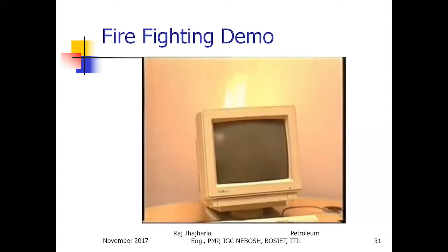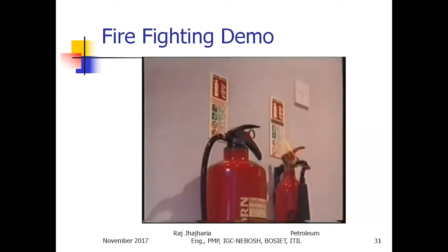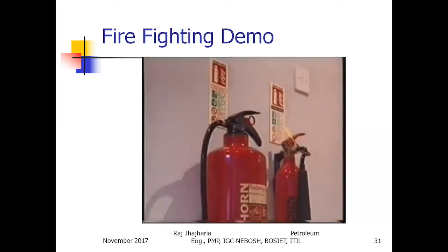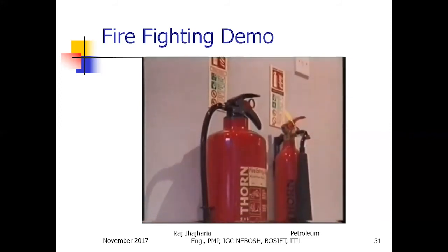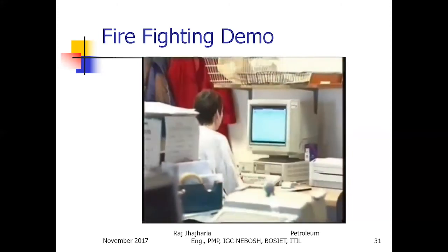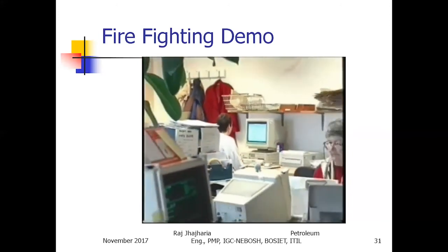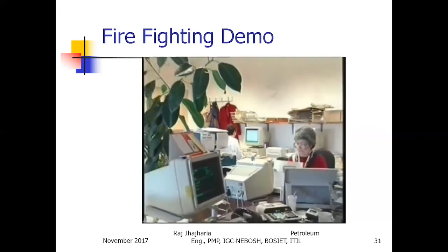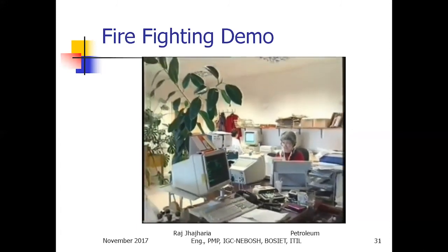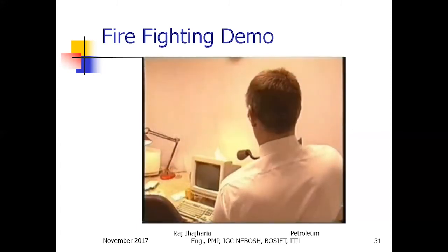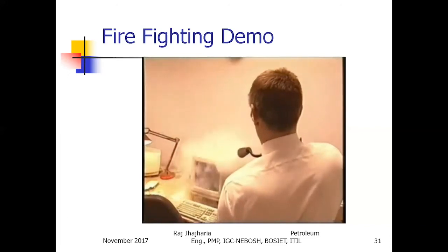Tackling a fire involving electrical equipment is likely to be one of the more common uses of the CO2 extinguisher, and in most cases where you find 2 extinguishers together, one of those will be CO2. CO2 provides a safe, non-conductive means of fighting the fire risks presented by the electrical risk in the modern workplace. It extinguishes fire by removing the oxygen and replaces it with a non-flammable gas.